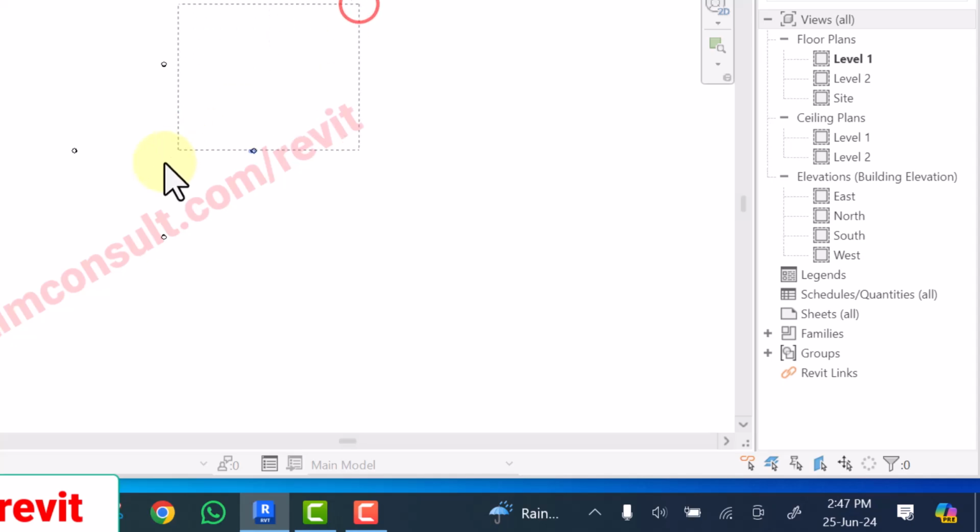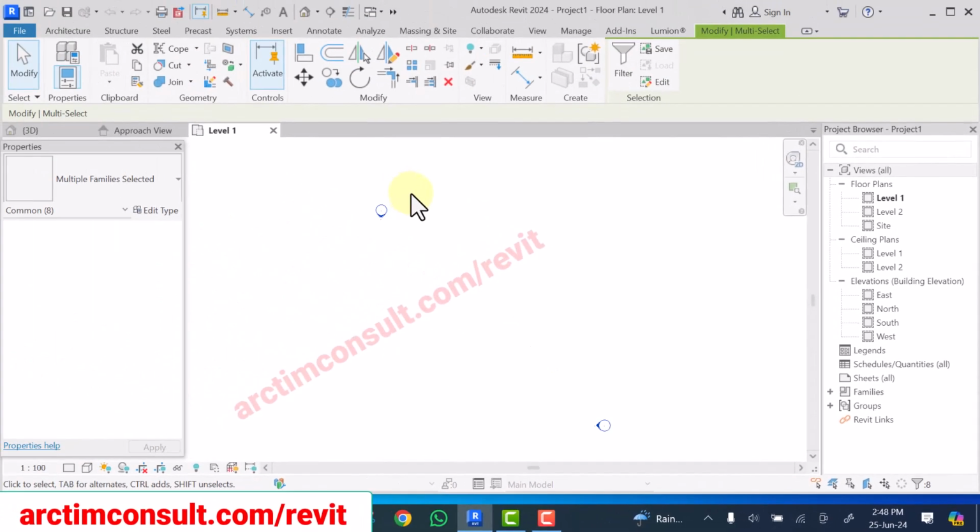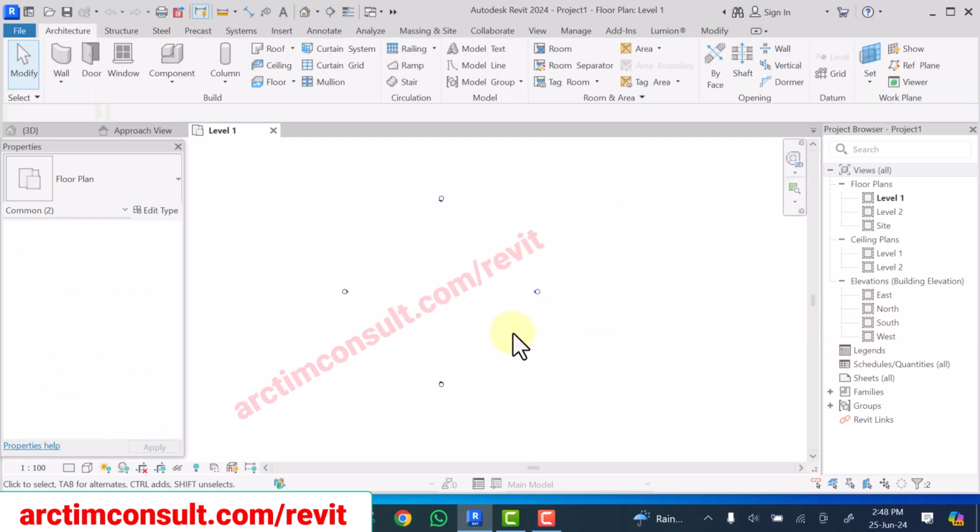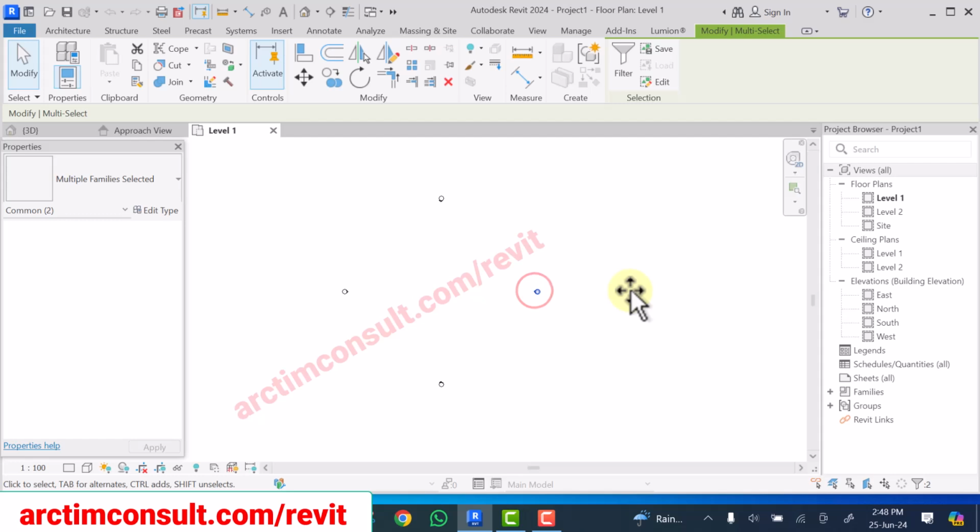Now what you have here are called elevation markers. These are what gives you your elevations. So don't delete them. You can actually move them backward if you have a fairly large project that cannot be accommodated within.